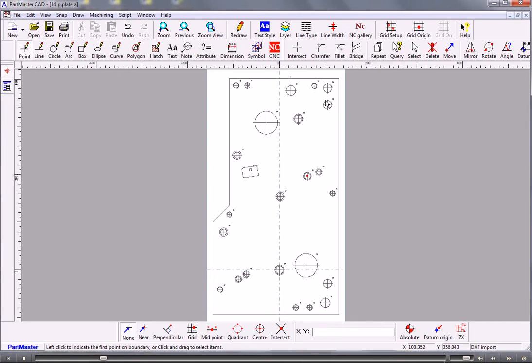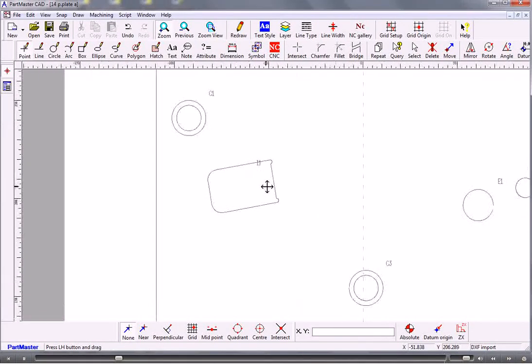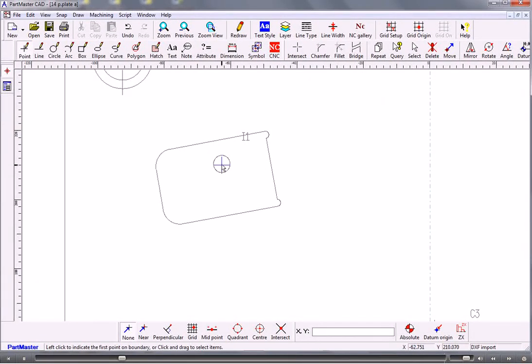So we need to create contours of maybe some of these holes and apertures, and also set where we want the data point to be. Okay, so before we start, I'll just zoom into this area here, because this looks like an aperture that we'll probably need to wire, and we'll guess that this is the start hole position. So what we need to do there is find a corresponding perpendicular spot on this line here to start the contour, and the way that we do that is to use the intersect function, and from the vertical toolbar here we use split and we use perpendicular.